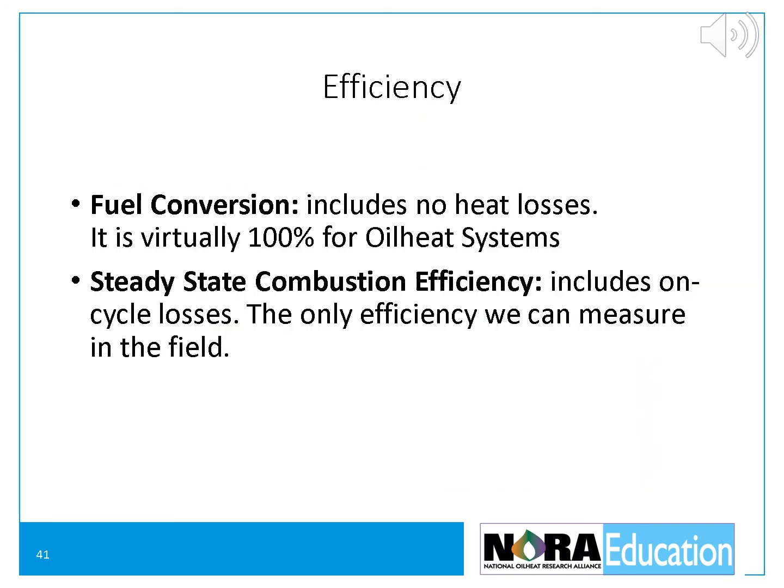There are many different types of heating systems and many different definitions for efficiency. Fuel conversion efficiency is the percentage of the fuel that is converted to heat in the flame. If the burner is set for zero smoke, then all the fuel has been burned and the fuel conversion efficiency is almost 100%. There's no unburned hydrocarbons left in the combustion gases.